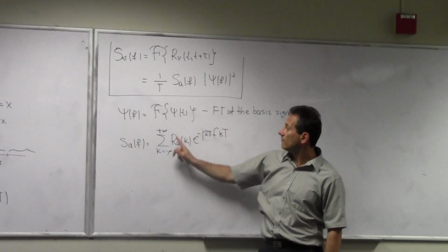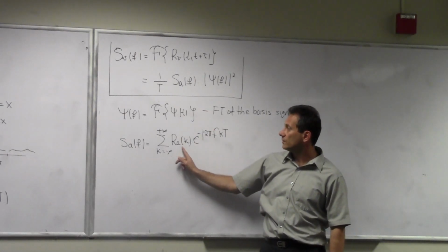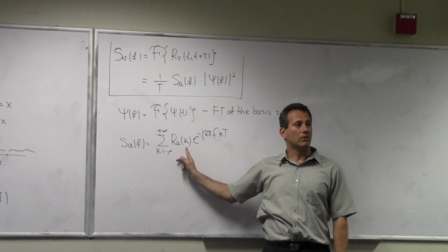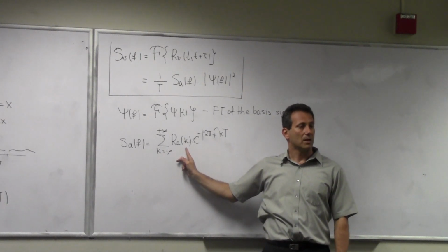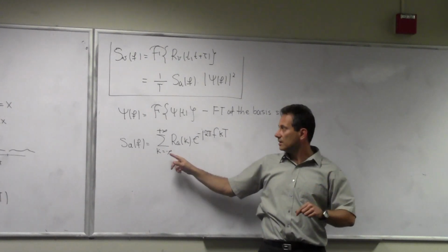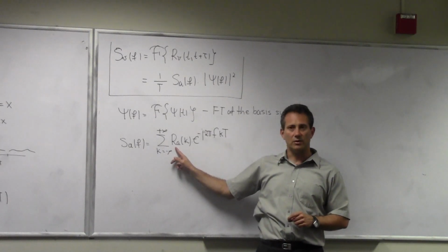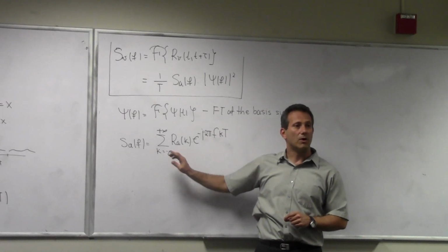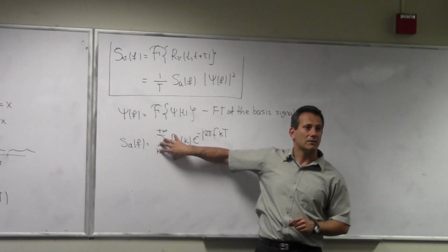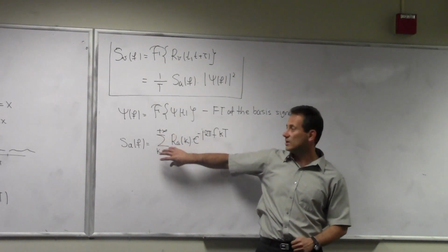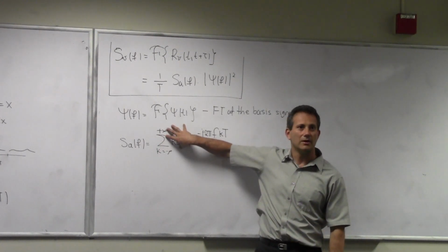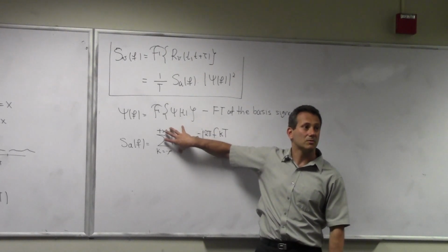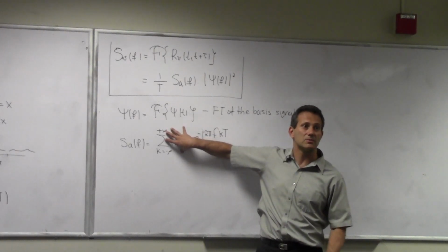This is the Fourier transform of the autocorrelation function of your sequence. Now, we said earlier that most of the time, through our coding, we're going to make this autocorrelation function look like what? A delta pulse. So what is the Fourier transform of the delta pulse? Constant. So even though this looks scary, for the most part we will design our systems for this to be constant.